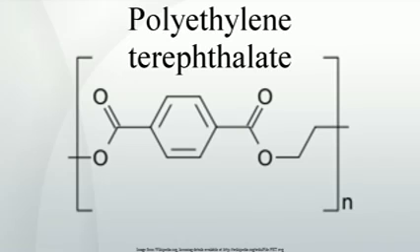gel or fisheye formation. Discoloration is due to the formation of various chromophoric systems following prolonged thermal treatment at elevated temperatures. This becomes a problem when the optical requirements of the polymer are very high, such as in packaging applications. The thermal and thermoxidative degradation results in poor processability characteristics and performance of the material.